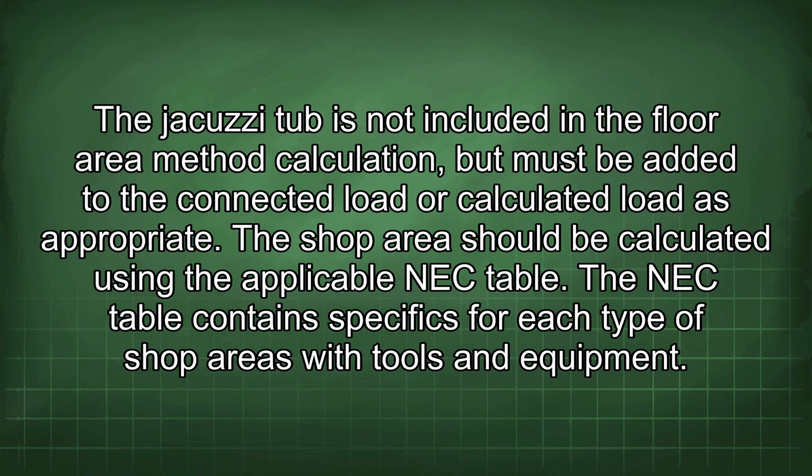The jacuzzi tub is not included in the floor area method calculation, but must be added to the connected load or calculated load as appropriate. The shop area should be calculated using the applicable NEC table. The NEC table contains specifics for each type of shop area with tools and equipment.